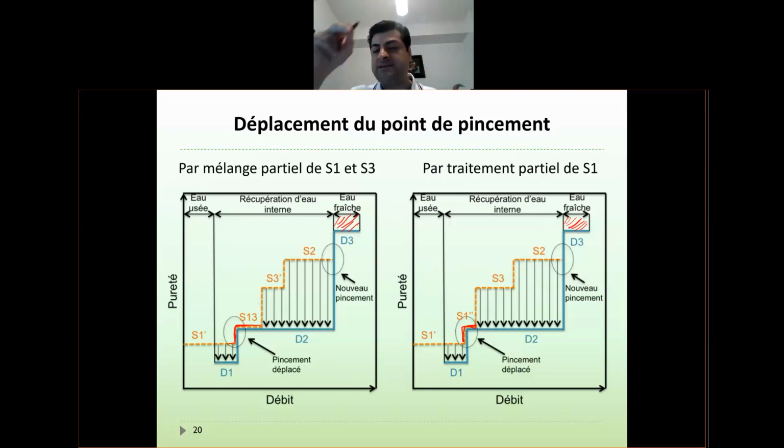As you saw, by shifting the delta T to different values, at the end the total cost has a decreasing and then an increasing trend. And that minimum point of the valley is usually associated with the delta T that we have to take. For water pinch, optimization is a bit different. It's different because here it is not based on delta T.